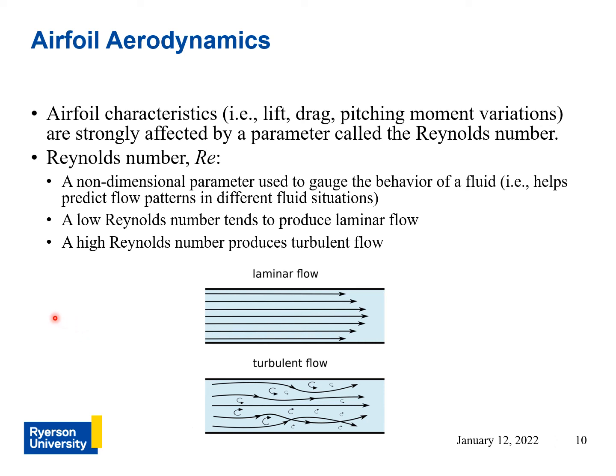Knowing the Reynolds number, in other words, the flow regime at which you're going to fly, is important because you can't use the airfoil data obtained at one Reynolds number and apply it to an aircraft that'll be flying at a totally different Reynolds number.